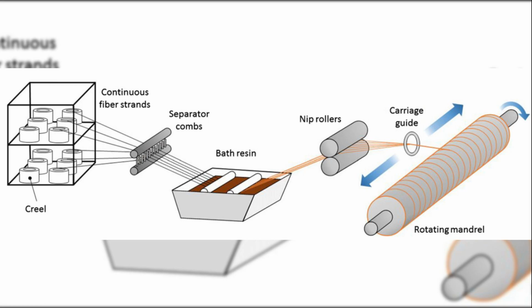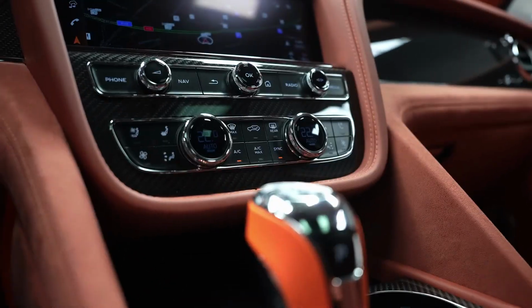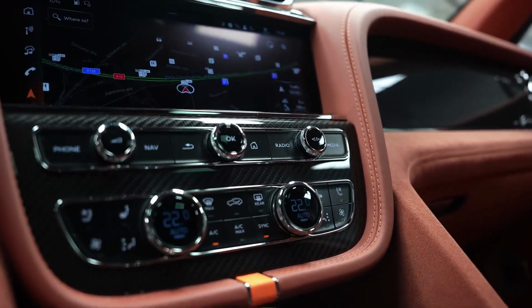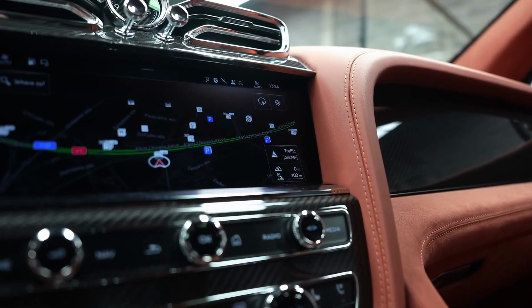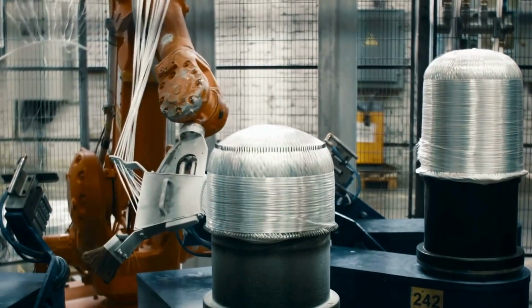First, it protects the delicate filaments from mechanical damage during handling, winding, and further processing. Even though carbon fibers are extremely strong when stretched, individual filaments can be damaged by friction if left unprotected. Second, the sizing layer improves compatibility between the carbon fiber and specific types of resin systems used in composite materials. Once the fibers have been treated and coated, they are wound onto large spools. Each spool may contain several kilometers of continuous fiber.